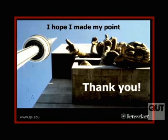So even though the reduction in amplitude was fairly small with the continuous jet, with the pulse jet, we actually anticipate much better response, and the PhD student who'll be defending next week for me has done a whole lot of computational work. We've done some calibration of this computational work, 2D and 3D. I've yet to see the results in turbulent flow. It's been more or less uniform free stream flow. But there he's seen 40% reduction in crosswind response, the RMS, by pulsing the jet, by using resonance. And that frequency is about 10 times the vortex shedding frequency.